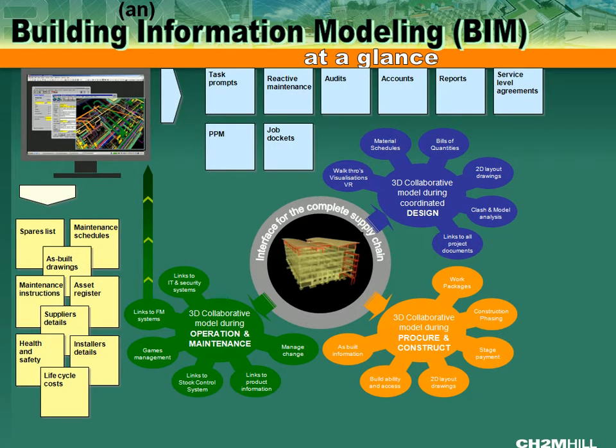During operations, we now have a robust as-built model, 100% representing the physical built form. So from that model, operators can create simulations with respect to security, safety, and training, and also attach maintenance information to the model based on the components, spare parts list, instructions. They can create a linkage to their local asset register, so that however they're monitoring their assets, they can have a direct linkage to the virtual BIM model to understand where those assets reside within the facility.